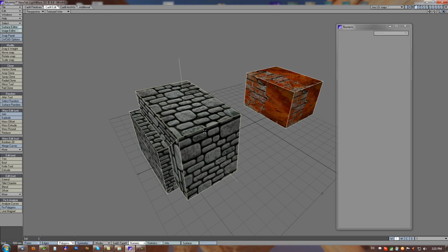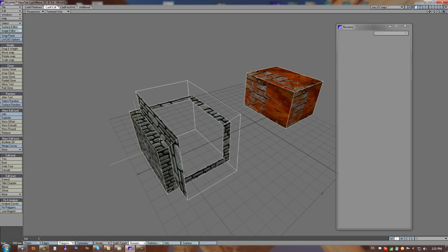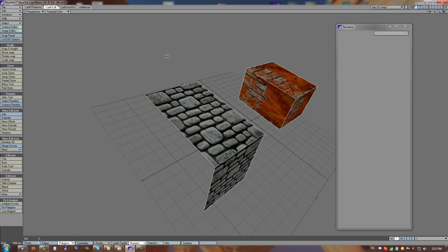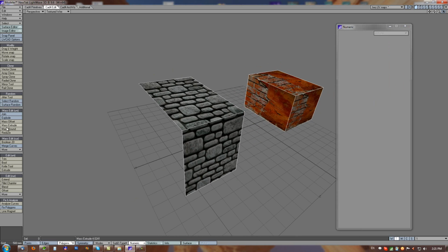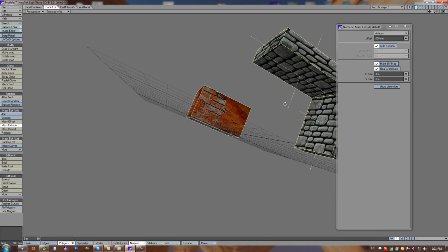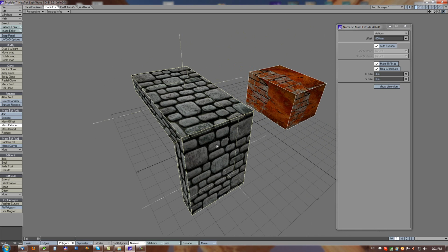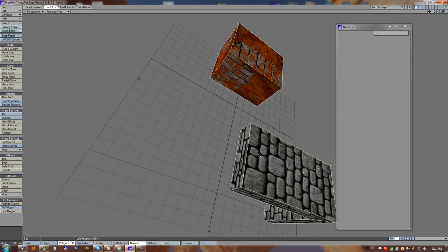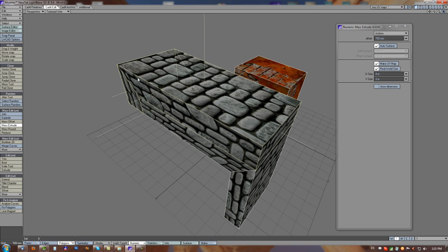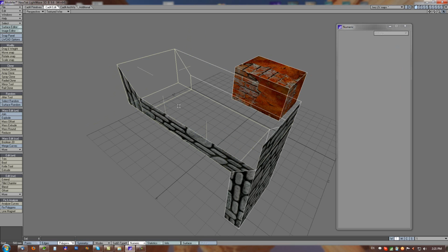When I use mass extrude on this not closed object, not a volume object with open edges, then mass extrude will close the object, so we create a volume object from a flat object. If it is used on an already volume object, then the back polygons are not created, so it will just extrude the existing object, so no additional polygons are inside.